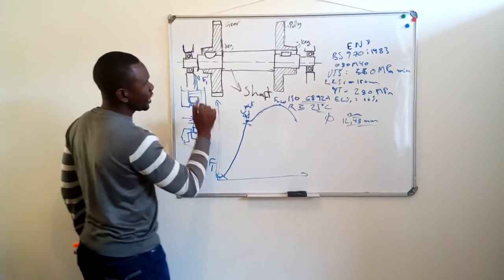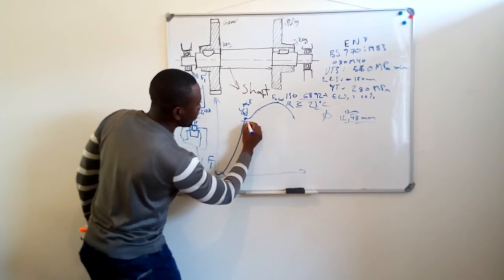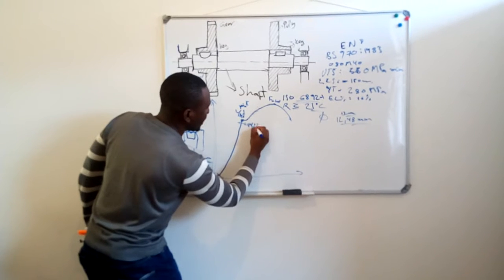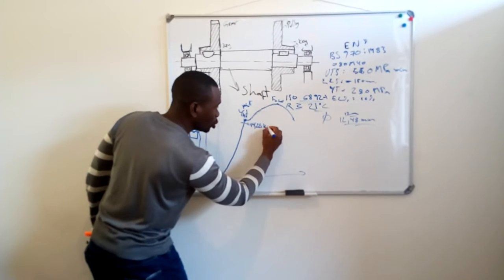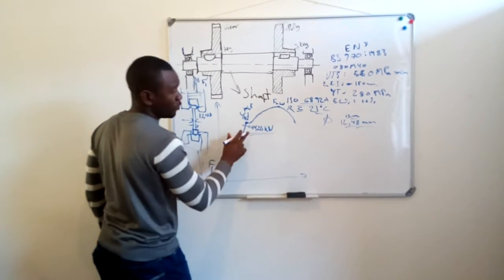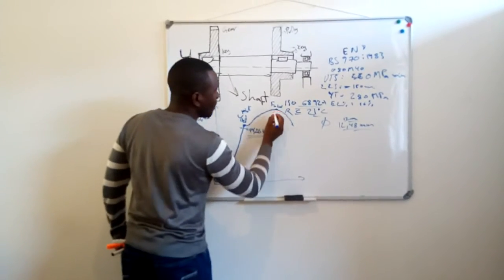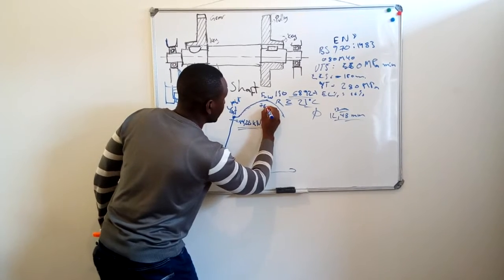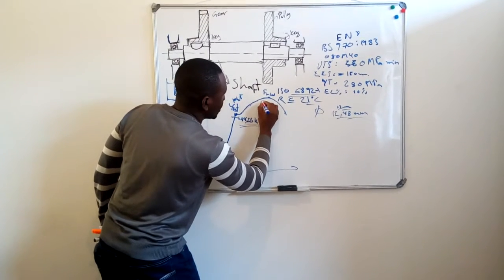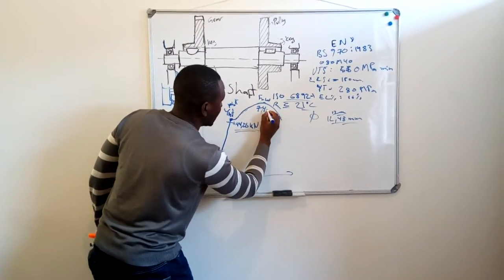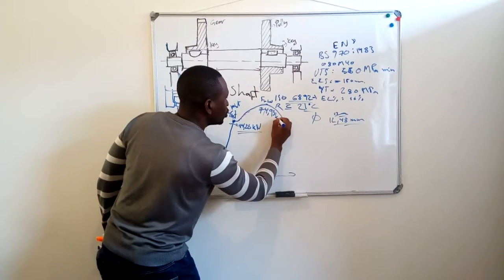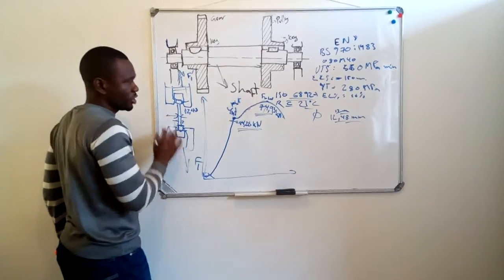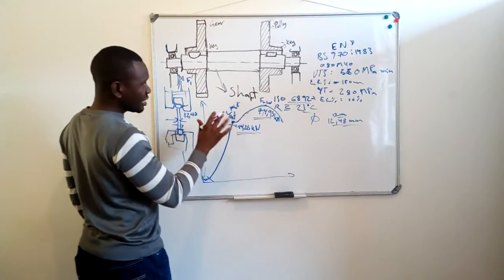While testing, we realize that the yield point is 44.28 kilonewton, and the maximum load is 74.93 kilonewton. That is the maximum load this sample can withstand before it breaks. And then this is what's going to happen.